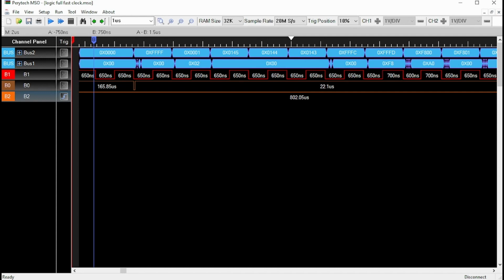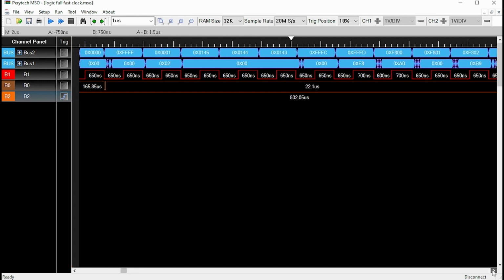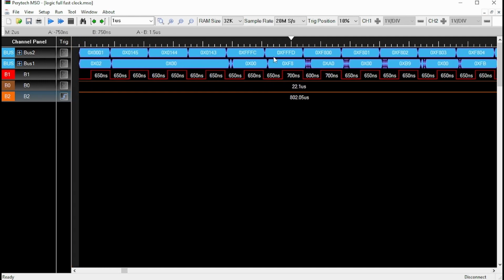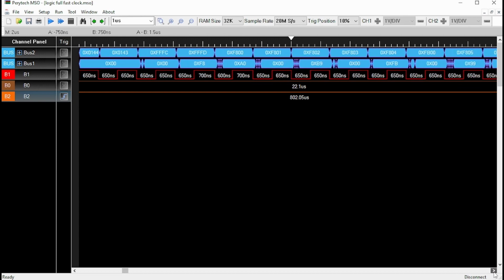So this is the same as we saw before. It's the address lines and data lines of our test circuit with the logic analyzer. But this time, this is at 1 megahertz. So it's looking similar. We start off with our FFFC, FFFD, and we've got 00 here and F8, so that's good. So we're picking out the correct address. And if you look at the address line, it's pretty good. We're not seeing any oddities there.